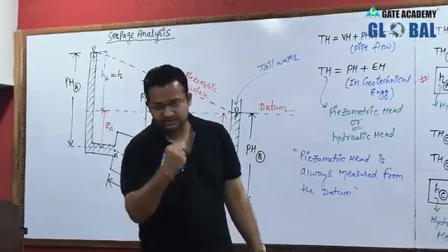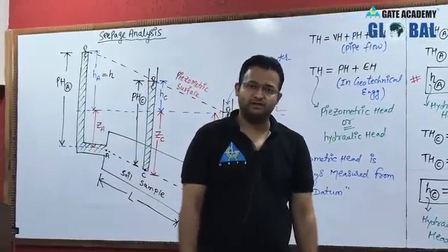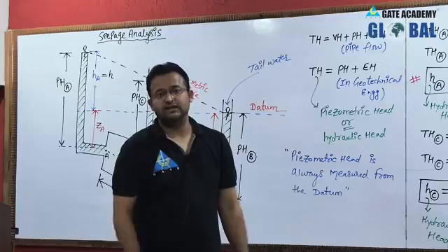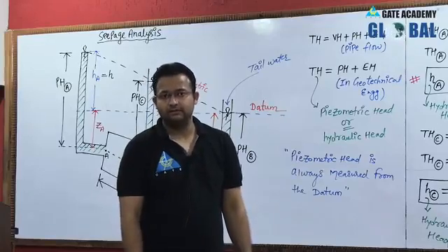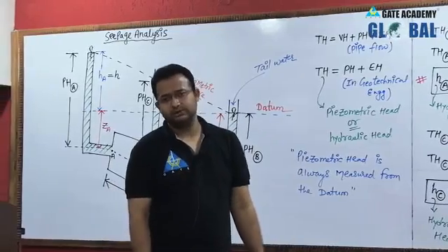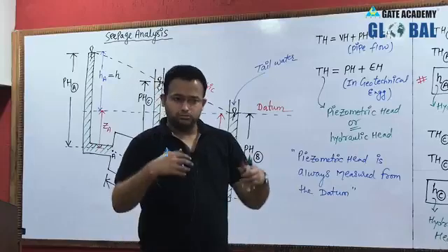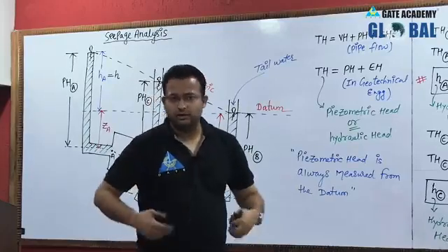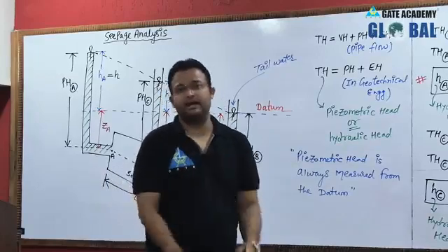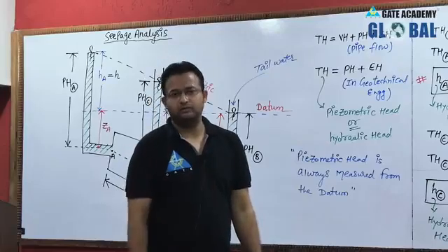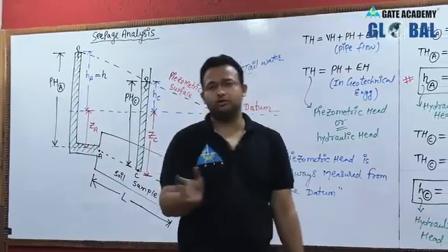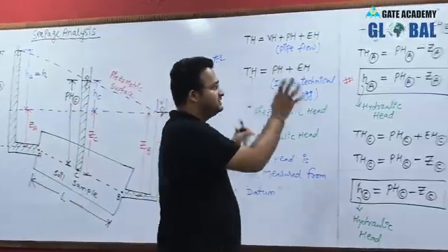So your soil should have stiffness and strength. Now how will you achieve that strength? By compaction. We will discuss in the next chapter, chapter number 3, about compaction, consolidation, stiffness, treatment. So many things may happen and so many things we can do also. So by increasing the effective stress of the soil, by compacting the soil, we can make the soil stiff, we can make the soil dense. Dense soil we want, so that because of seepage, your soil solids should not flow with the water. Okay, this is the seepage pressure.